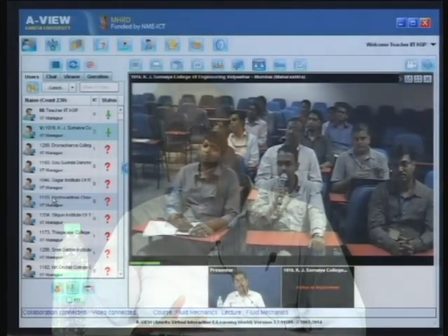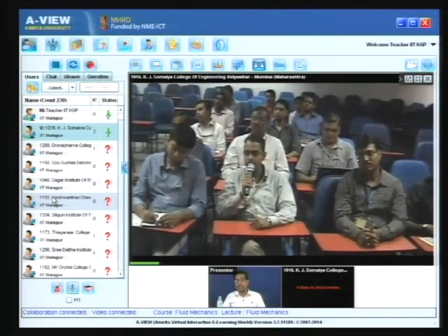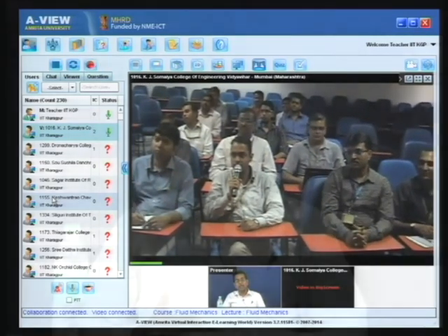For example, when the head is low, then to get some substantial power, you have to devise a turbine which must accommodate a high flow rate. So, a turbine which delivers power at a lower head and higher flow rate has to work on the principle of reaction. If it works on the principle of impulse, as in a Pelton wheel, the Pelton wheel acts in the situation where the head is very high, that means the reservoir is at a great height, at high altitude. So, there it is possible to convert all the potential energy into kinetic energy thoroughly and, by the impulse action, develop power efficiently.